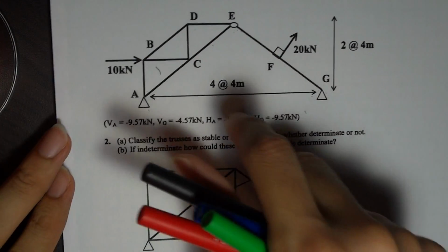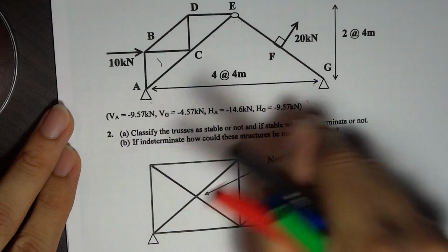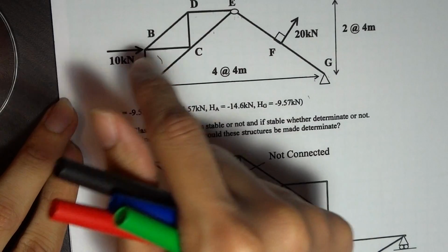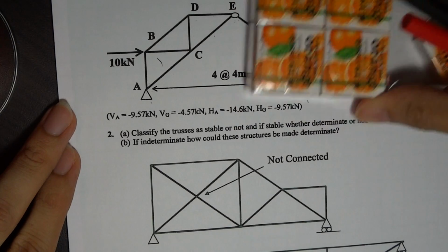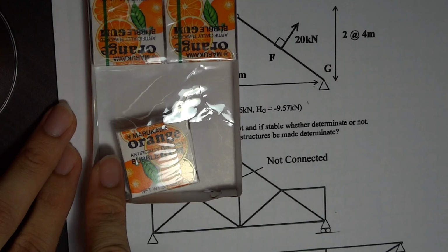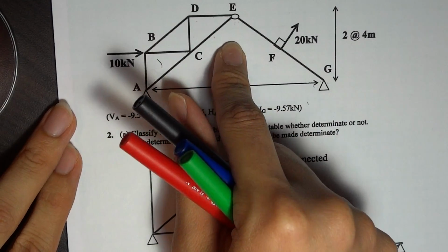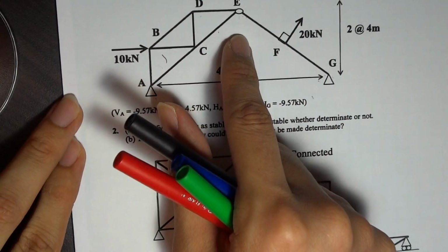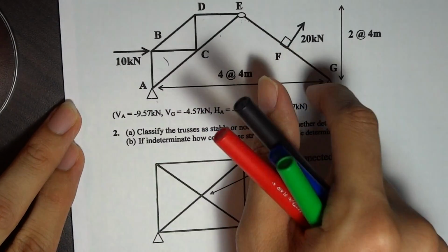So let's start. You're actually looking for the reactions here, which are technically kind of given, but you need to derive these yourself. You're looking for the axial forces in the truss members. So this half of the structure is a truss, and the other half of the structure is a beam. The member forces in a beam are the shear and moment diagrams. So you need to find the shear and moment equations also. You need to find the equations and preferably also draw diagrams for this member.